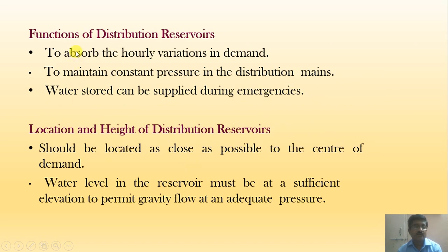Now, what are the functions of the distribution reservoirs? To absorb the hourly variations in the demand. So throughout the day there is a lot of variation in the demand of water, so that can be compensated by the distribution reservoir. To maintain the constant pressure in the distribution main, water stored can be supplied during emergencies.